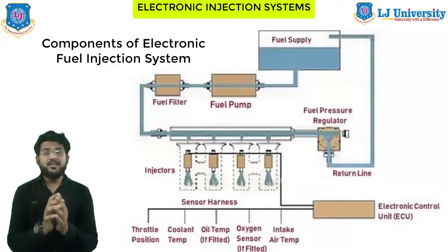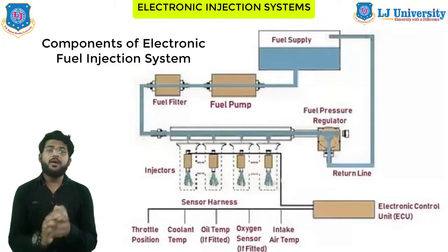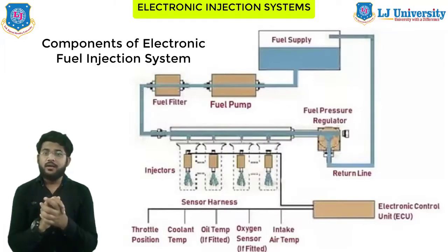Next is the check engine light, or service engine soon light. What is its function and how is it required in EFI? The check engine light is on the dashboard console, comes on during the scan and goes off when all the sensors are functioning perfectly. So this was about that indicator light. Next is the fuel injector.